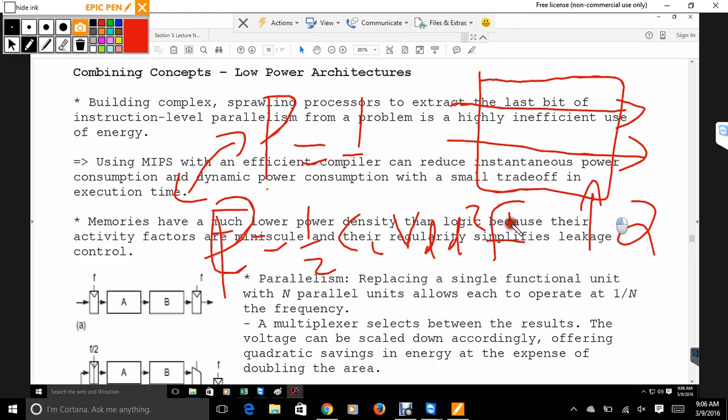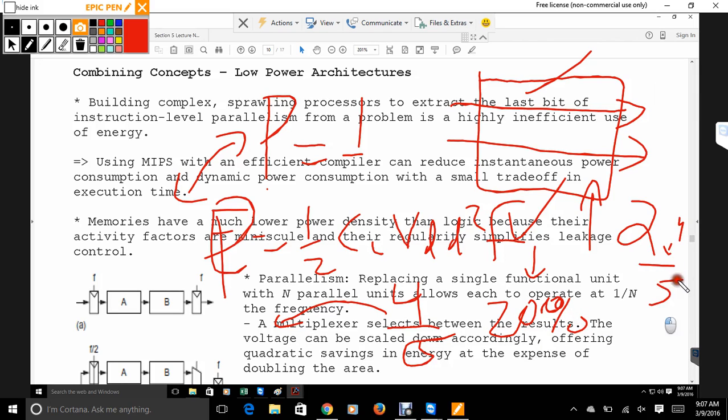You can decrease the frequency, because we've increased the throughput so much that I can decrease the frequency by some smaller factor. Let's say I decrease the frequency by 4/5, so a reduction of 20%. But because we've already multiplied by 2, it's just 2 times 4 over 5, so it ends up being 8/5, which is still significantly better than the 20% loss, right?